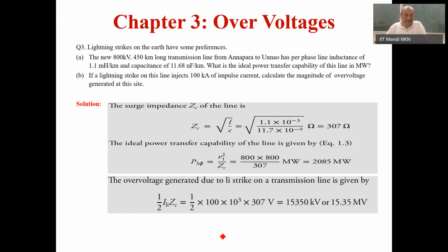The surge impedance, as I mentioned, we call it ZC. C is taken from characteristic impedance. Surge impedance or characteristic impedance is the same thing, two names for the same thing of the transmission line, and that varies for practically all transmission lines between 250 and 350 ohms.